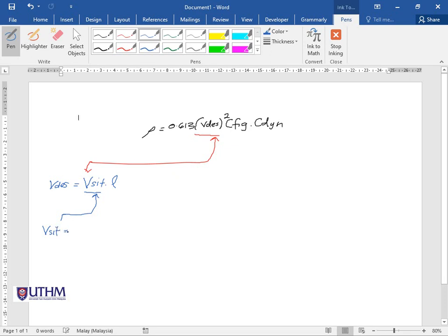V site equal to Vs multiplied with Md, the wind directional multiplier, multiplied with Mz,cat, the terrain height multiplier, multiplied with Ms, the shielding multiplier, multiplied with Mh, the hill shape multiplier.